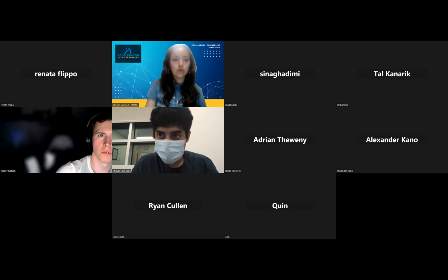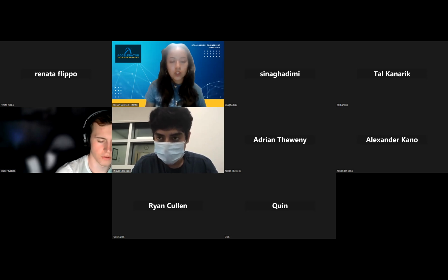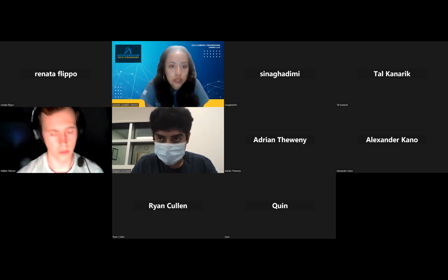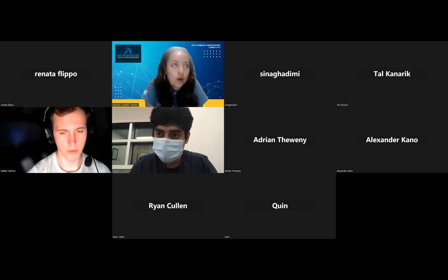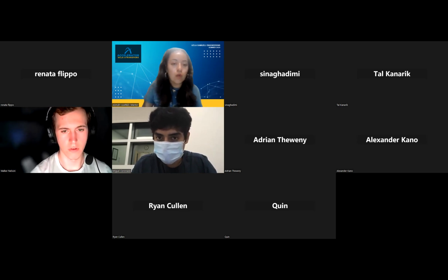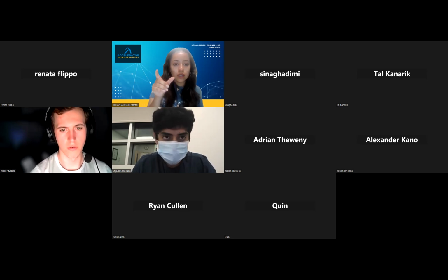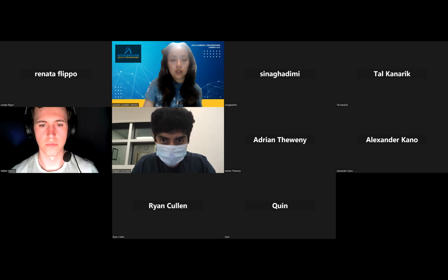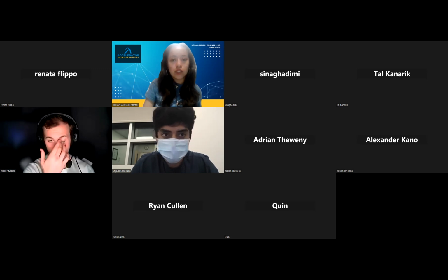Okay. Let me start by sharing my screen. Oh, sorry, I didn't see the chat. Simple file should be open. Start by opening a part file and create your cube. Create one cube, call it example cube when you save the file. And then once you are done with that file, open a new file, make it an assembly. And when it asks you to insert components, select the example cube file that you just created. Once you guys are ready, go ahead and send ready in the chat and I will start.